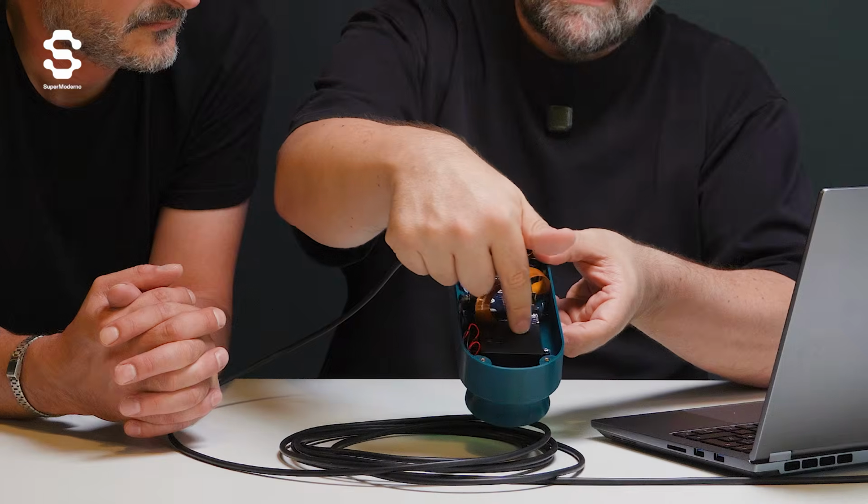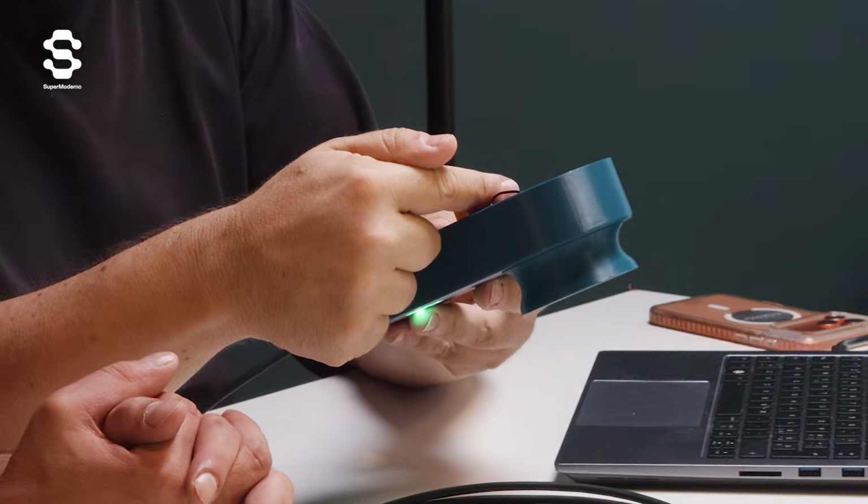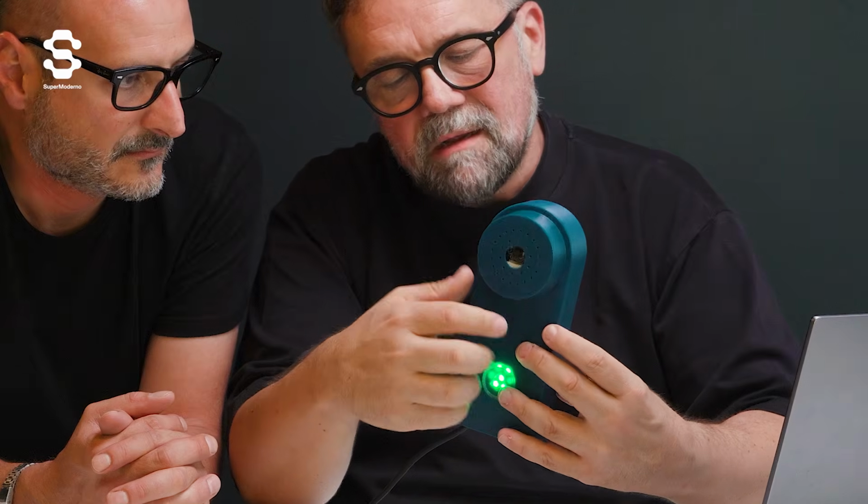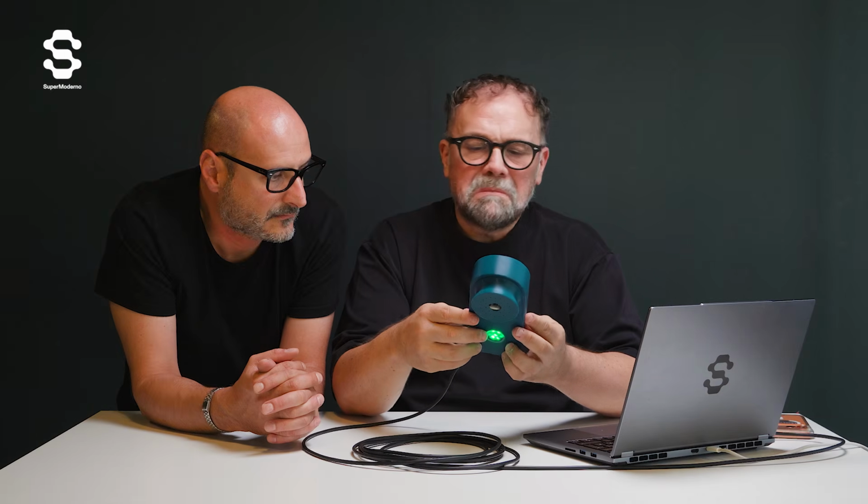So this alleviates the Linux machine from dealing with these LEDs, which need very, very precise pulses. Then we have a touch sensor, which at the moment is a little bit lacking in discipline, but we're gonna fix it. And then underneath here, there is the audio amplifier. There's a tiny hole in the box. This is where the audio comes in when you speak. And then there is a speaker here in a little plastic box that amplifies the sound. So the audio amplifier drives this, and you can hear it from here. And the camera is using an IMX219 Sony sensor. It's probably the one that's best supported by Arduino UNO Q at the moment.